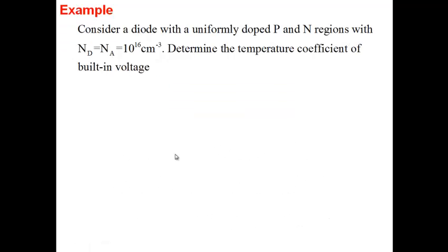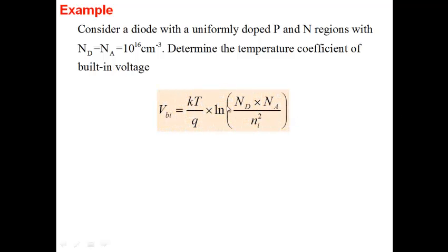This is more interesting. Determine the temperature coefficient of built-in voltage. Temperature coefficient. VBI is here. First of all, is the temperature coefficient positive or negative? Temperature coefficient means as I increase the temperature, what is the change in VBI?